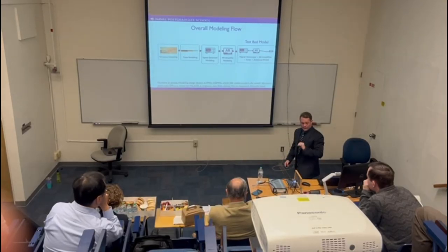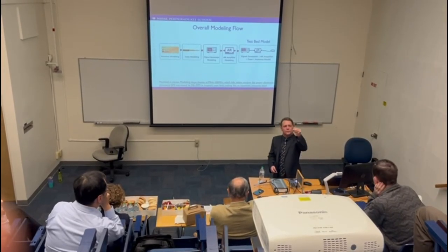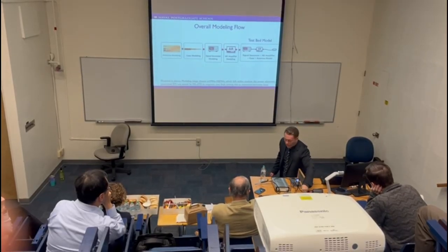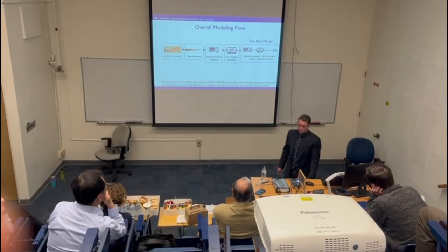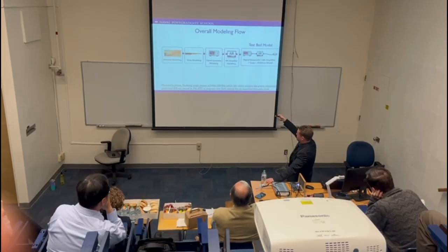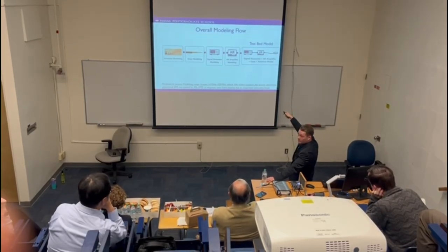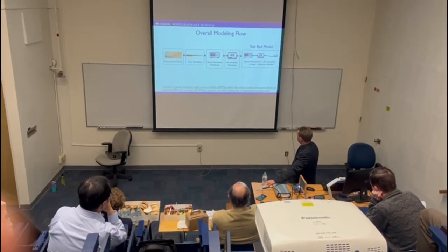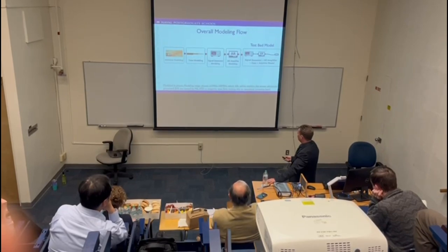Then what that gets connected to is a coax. So this is a tiny little coax here, a little 6-inch coax. But that's the next part that I needed to model, RG58 coax. Then I had to model the actual signal generator. That signal generator could amplify the signal into the AR amplifier, which was the next step. I had to model the power amplifier, the 100 watt power amplifier. And then as a whole unit, I'm able to model the actual full test bed.